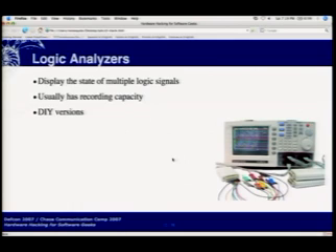You can make a do-it-yourself logic analyzer. I also have kits for that. Since we have the question and answer room, I'll be giving some of these kits out there. They hook up to the parallel port and can watch 8 lines at once. Due to the relative slowness of the parallel port, they get about 1 million samples per second, so they can't pick up a signal much more than 1 megahertz. Well, actually it has to be much less than 1 megahertz.